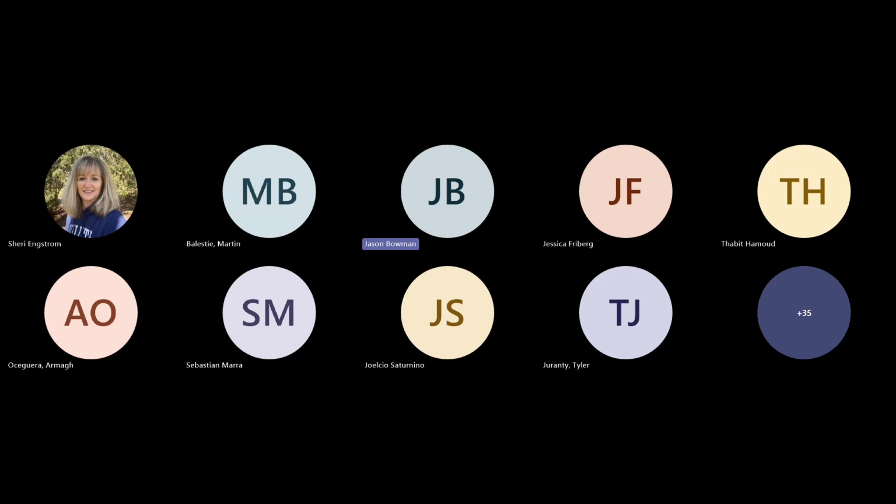Just out of curiosity, from Roberto, have you ever verified the SVI of the anaerobic sludges? Yeah, we have a lot of data on different operations. Not to get too far sidetracked, but we still have the classical digesters, the CSTRs. We have the recuperative thickening units as well. It's kind of all over the map. Every industry is a little different. Some industries will have the whey factored into the equation. Other sites, it doesn't make sense to add the whey to the rest of the process. So all that impacts the balance at the end of the day, and whether or not we have a downstream biological system after that for further clarification or further biological treatment.